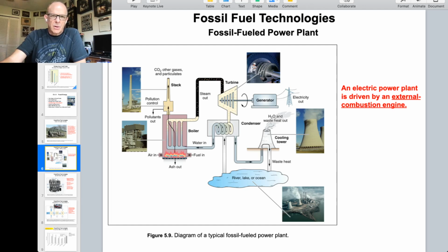And you'll remember from the laws of thermodynamics that to make that power plant more efficient requires a very big temperature difference between the thermal energy going into our machine and the cold side on the other side of the machine, which is the environmental temperature. So we want to make that steam as hot as possible.